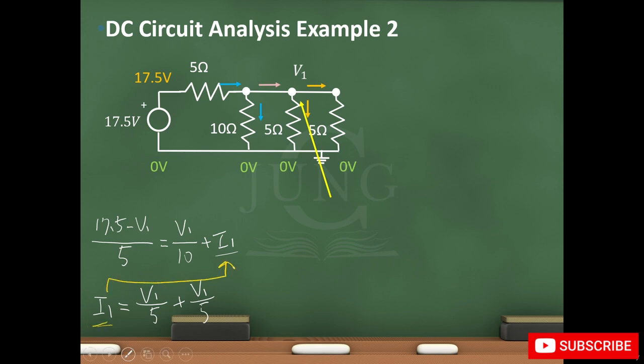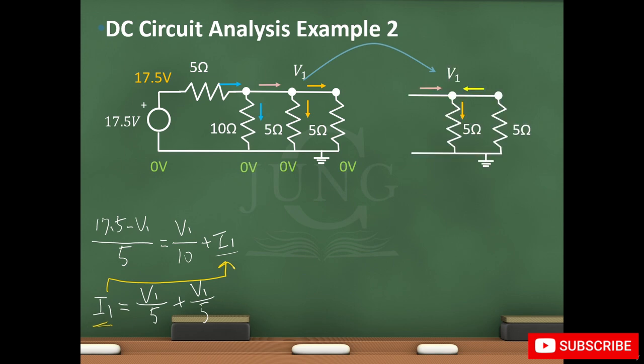But before we solve this, I just want to quickly show you why it doesn't matter which directions you assume the currents to flow, as long as it's consistent when you apply the Ohm's law. Let's focus on this second junction again. If now I assume the current flows in these directions, again we'll have the current flowing in, so I1 plus I yellow, equals the current flowing out, I orange.